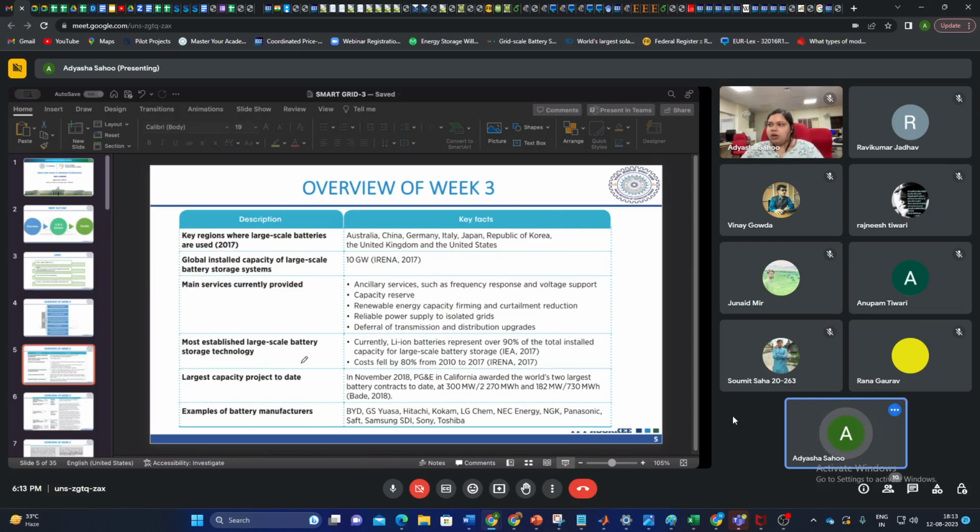So basically, for managing our power system, which is dynamic, we always need to have reserve with us, so that when we have need for power, these reserves can be activated. The storage can act as a reserve because of the intermittent nature of renewables. So energy storage is a must to provide adequate reserve, so that it can charge or discharge according to the need of the grid. They will also provide firm capacity.